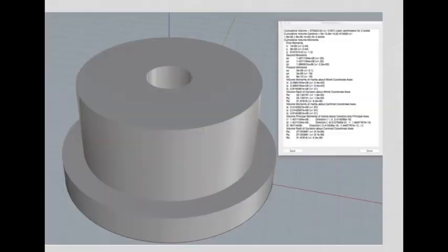So we work out that alpha, the angular acceleration we're dealing with here, is 0.1151 radians per second squared. And this angular acceleration is final angular velocity minus initial angular velocity over time. So the time that it will take for this to happen will be 727.85 seconds, which is 12.13 minutes.